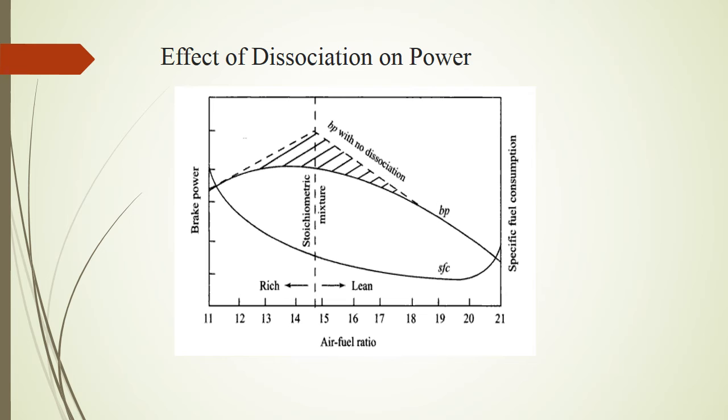It has been observed that dissociation effects are not so pronounced in the CI engine as in the case of the SI engine. It is basically because of the heterogeneous mixture and excess air present in the CI engine. Both factors will reduce overall temperature.